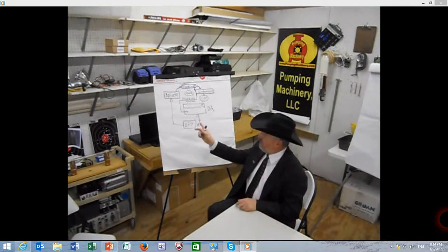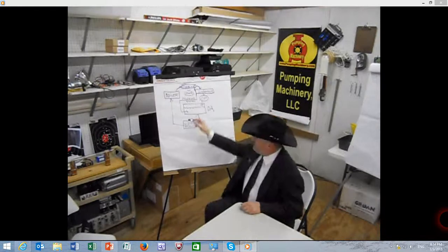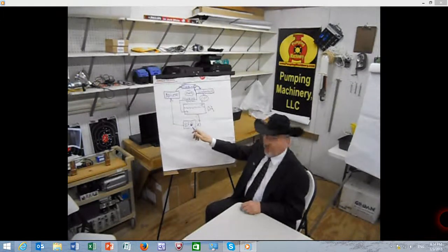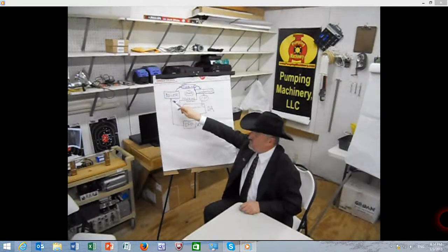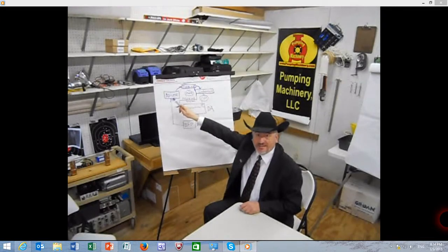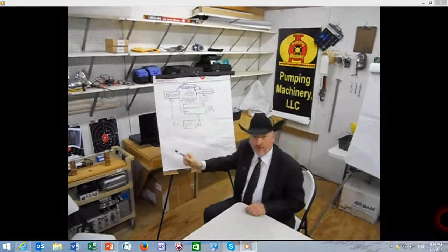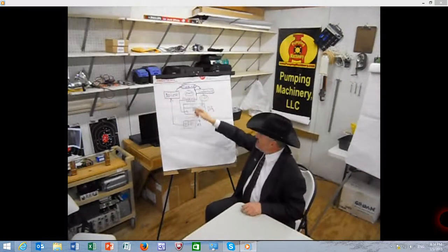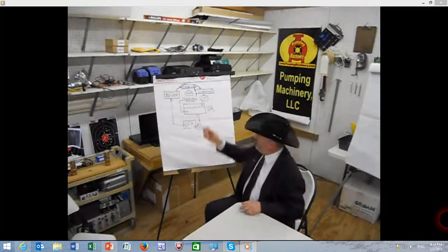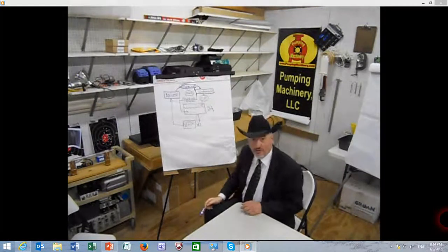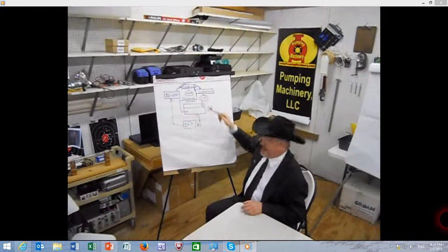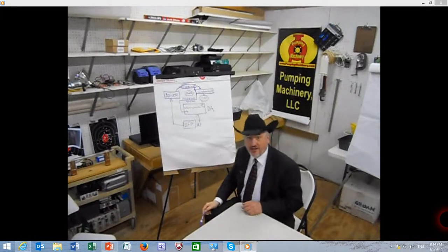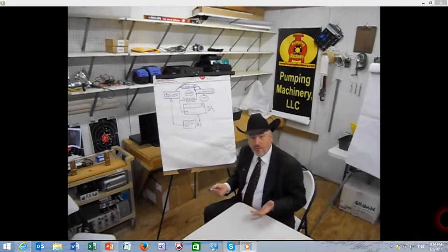We discussed it as shown in the diagram, which is a simplified view of the power plant, that the boiler feed pump feeds the boiler, which boils water into steam, and steam goes to a steam turbine to generate electricity, and then exhausts at low pressure into a condenser to condense back to water. And then on the way back to the suction of the boiler feed pump, it goes through the Deaerator for the purpose of removing air.